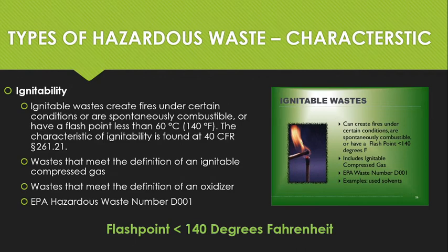It also includes waste that meets the definition of an oxidizer. So those are all things I'm looking for when you guys send me an SDS or tell me a product name. When I look up the SDS, I'm looking to see, is this an oxidizer? Does it have a flash point less than 140 degrees Fahrenheit? And if it does, then what we tack on there is D001. That is an EPA hazardous waste number that indicates that you've got a flammable hazardous waste. So if you're ever filling out a manifest and you see D001 on there, then okay, we know that it's going to be flammable hazardous waste.